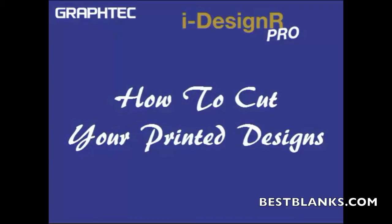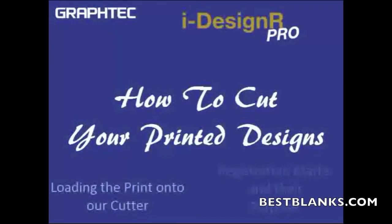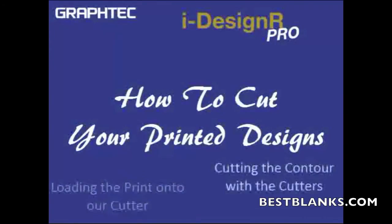In this segment, we'll give you steps on how to take your printed designs and, using your cutter, cut a contour around the printed design. What items are covered in this segment are first, how to create a cut line for both vector and bitmap designs. Second, we'll show you how to create registration marks and the purpose for them. Then, after we printed our design, loading the material, and finally sending the contour cut line to the cutter.